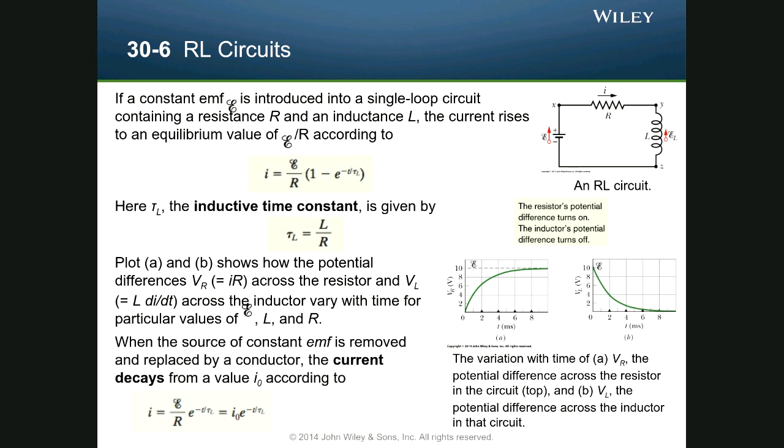with the resistance and the inductance, right? With the current going down. Now, you'll notice that you have your EMF battery, but you'll also have EMFs due to Faraday's law, right? You'll notice they kind of point in opposite directions. So when we do the loop law, we'll start at one point, we'll move around the circuit, right?